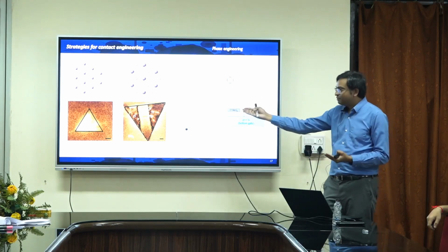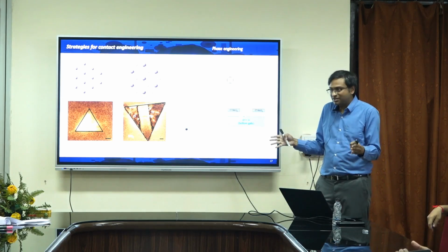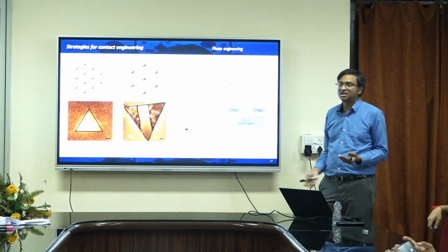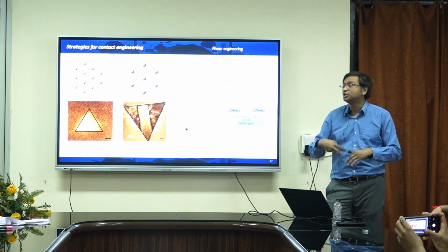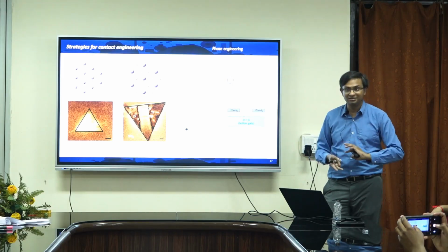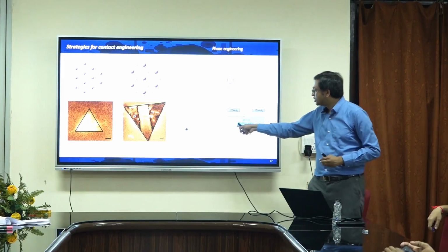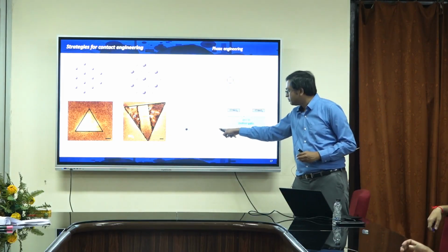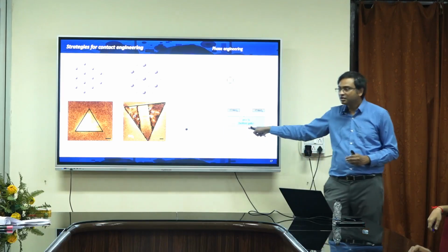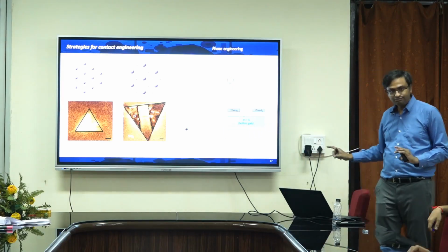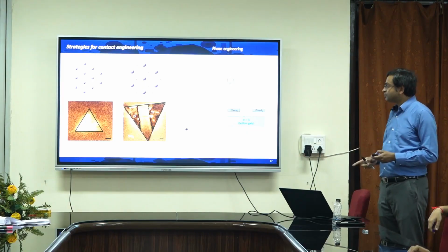So now you have a metal contact, atomistically clean, to a semiconducting material. This is like the selective area doping we were talking about, but instead of doping, they have literally converted it into a full metal, and they showed that the contact resistance could be low. The number is not bad. It is not 50 ohm micrometer, but it is still like 480 ohm micrometer. So that is one approach.